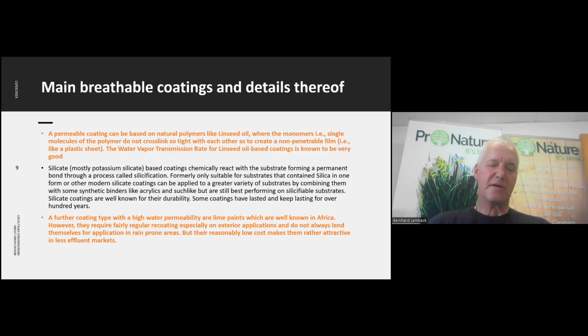Then the other group that I mentioned a little bit earlier already are the silicate-based coatings, which can actually chemically react with the substrate. So they're not really forming a film as such, but they are indeed very well known to allow for the release of moisture, and by adding various additives to the silicone coatings, we can also avoid the ingress of water.